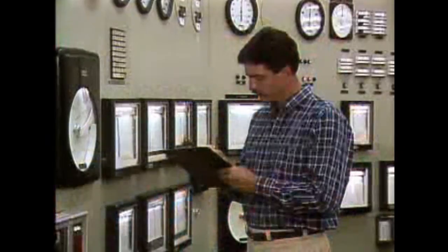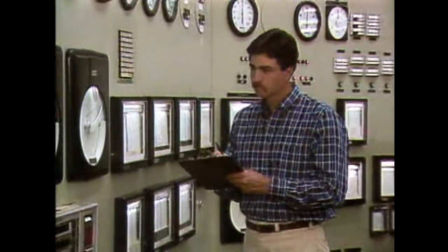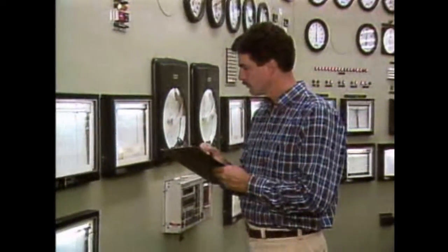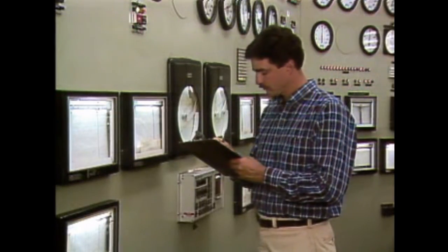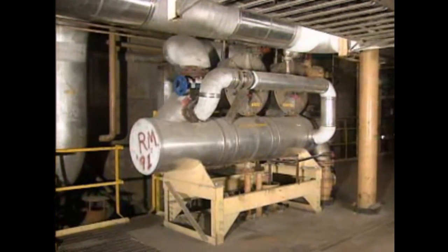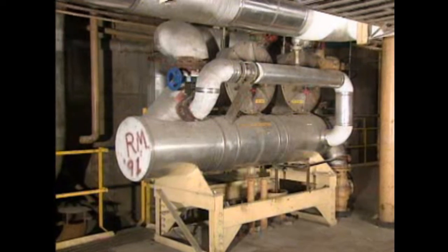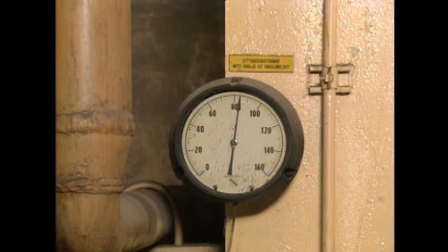However, since both your safety and the efficient operation of the turbine unit depend on them, periodic checks are needed. The Gland steam seal supply pressure should be checked to make sure that it is high enough to maintain the seals, but not so high that steam leaks from the glands. The temperature of the cooling water flowing through the Gland steam condenser must also be checked. The temperature must be low enough to ensure that condensation is occurring properly.